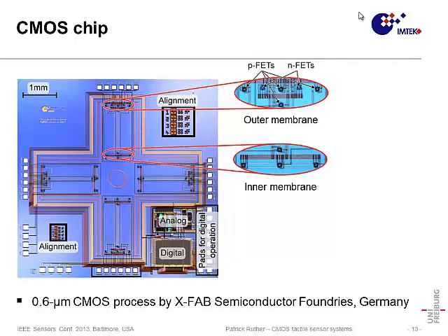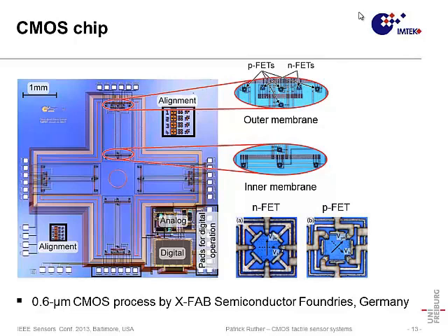And as mentioned before, we have 3 piezoresistive field effect transistor elements integrated in the membrane, plus a reference sensor. And on the outer membranes, we did, just for curiosity and for testing, additional shear stress sensors. So these are the FETs here, and they are accessible through additional contact pads here at the rim of the wafer itself, but they haven't been used in those measurements that I will show you later on. Yeah, and this is a detail on the stress sensing elements without a non-conducting island in the center.